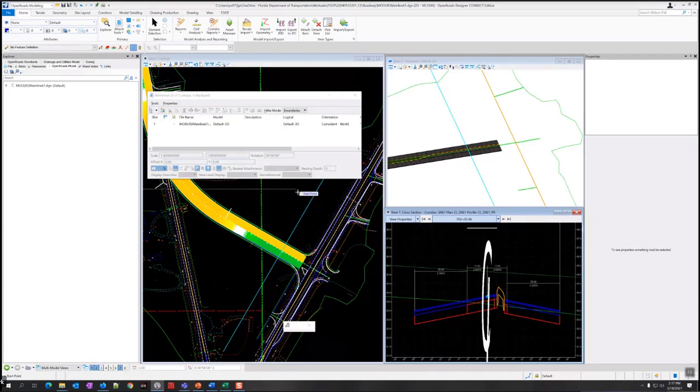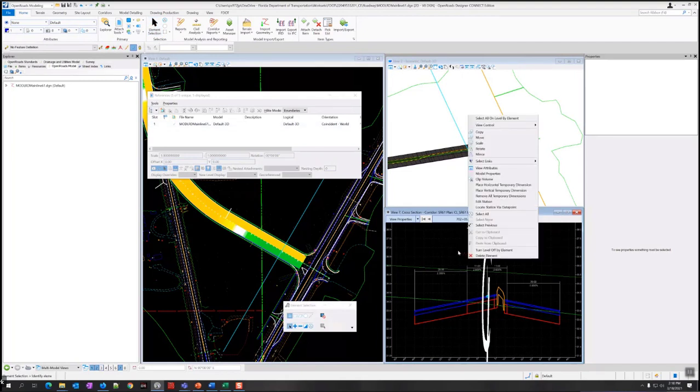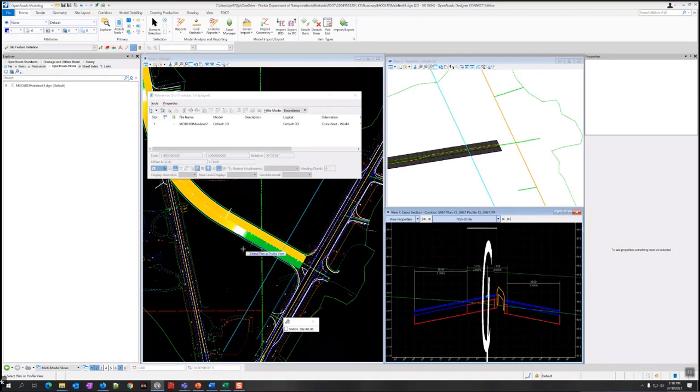And then over here, before I change the station, I just want to keep it here. So I'm going to go to view properties here and do center on current offsets. And then I'm going to go back and locate station by data point. So right click and hold. This is step 8 here. Going back to that. Okay, station by data point.